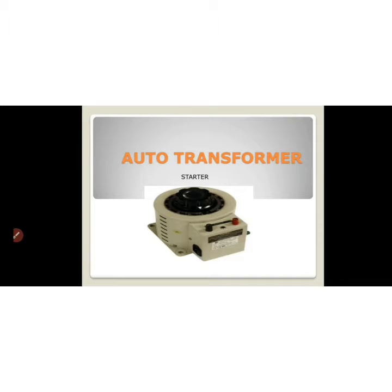However, such starters are providing output. In general, auto transformer tapping can be arranged in between 50% to 80% voltage. The starter of this auto transformer doesn't need difficult cabling because it is connected through 3 terminals simply.